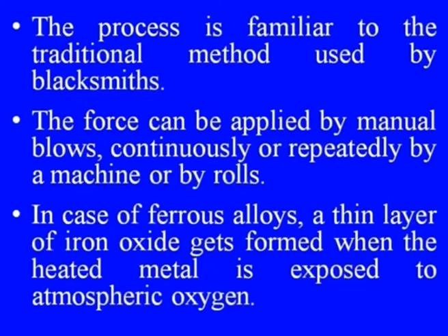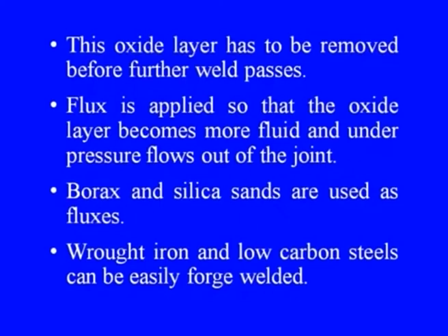In case of ferrous alloys, a thin layer of iron oxide gets formed when the heated metal is exposed to atmospheric oxygen. This oxide layer has to be removed before further weld passes. Flux is applied so that the oxide layer becomes more fluid and under pressure flows out of the joint. Borax and silica sand are used as fluxes.